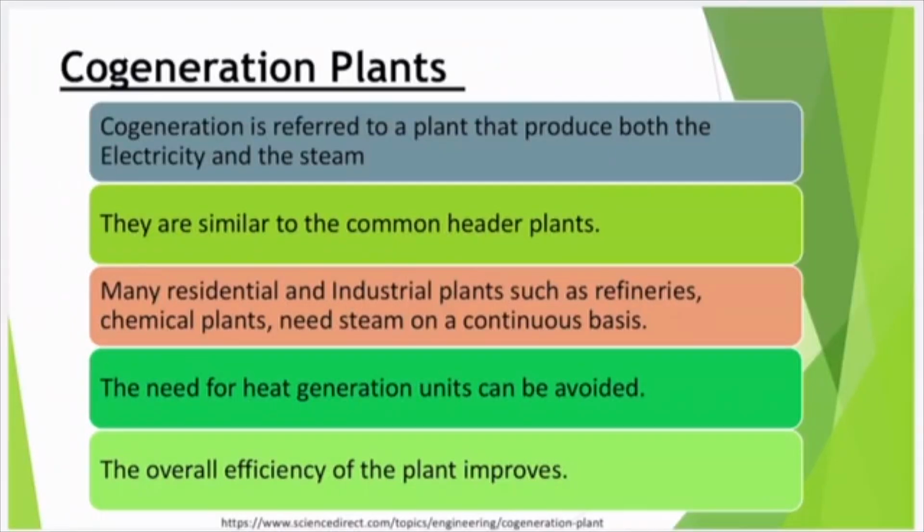Am I right? So what has happened, we generate electricity, and that electricity is being generated from heat, and then we use that output of the power plant electricity as an input to a device to produce heat further for our survival. So heat to electricity, electricity to heat will increase my loss, or the efficiency gets reduced significantly, because if input-output of heat to electricity is 70% and electricity to heat is 80%, then the complete system is operating at close to 60%, even below that.